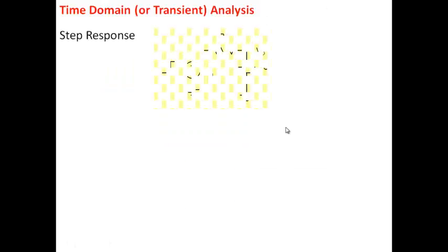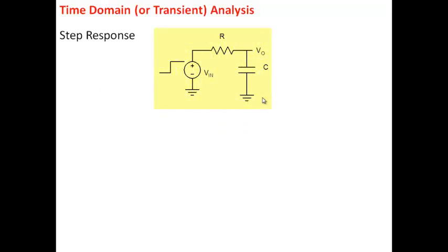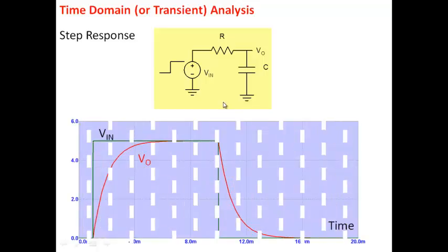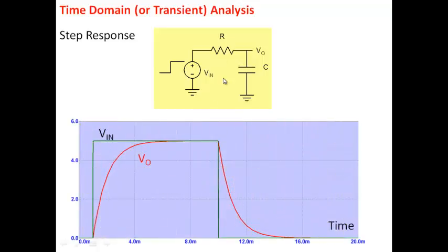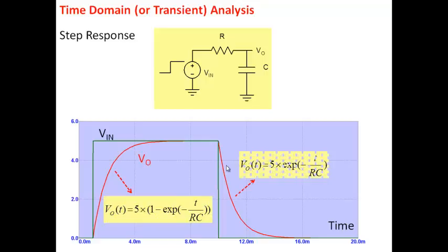All right, in the time domain, we don't normally encounter this in amplifiers because most of our signals are small signals. But you know that if you excite your RC circuit by a step, then what you get is exponential charging and exponential discharge. And then you can define charging time and discharging time, rise time and fall time, and they are all related to the RC time constant, which is also related to F3dB. Okay, so the two are related. How much time does it take to charge? How much time does it take to discharge? Inversely related to F3dB. All right, so that was low pass.